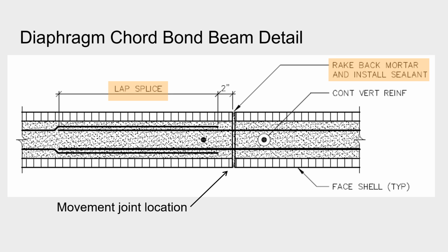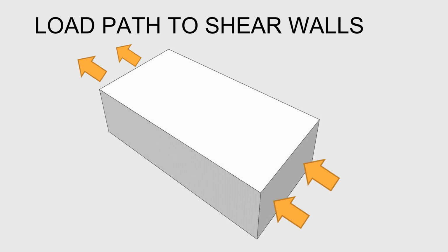For more information, see the National Concrete Masonry Association's Tech Notes. Tech 10-2C specifically provides construction details for movement joints. Engineers should analyze the bond beam using the reduced width of the joint as well. Here we see the previous example building, but now we're reminded that we must look at the diaphragm from the perpendicular direction also. This will give stability for all the walls.